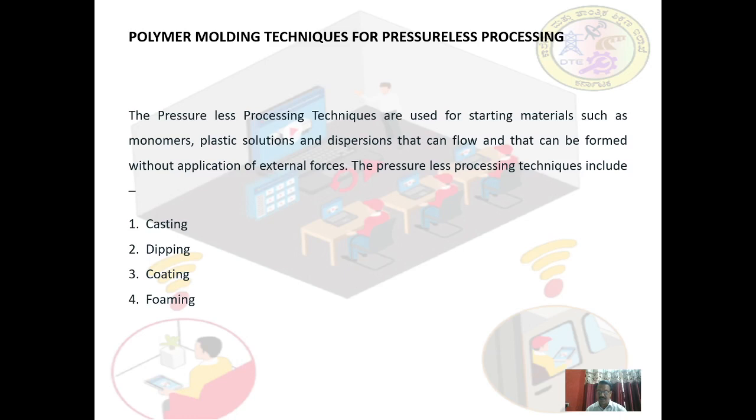The only difference is that in rotational casting, the PVC paste is metered into the mold, which makes the removal of excess paste and post-gelation techniques redundant.